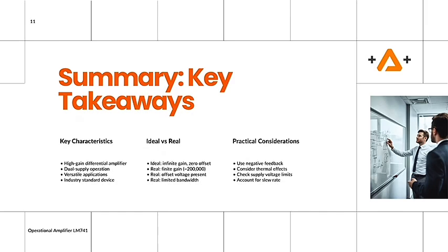Ideally, these currents should be 0, but real operational amplifiers require a small amount of current to operate correctly. Furthermore, the difference between the currents at the inverting and non-inverting inputs leads to what is known as the input offset current.